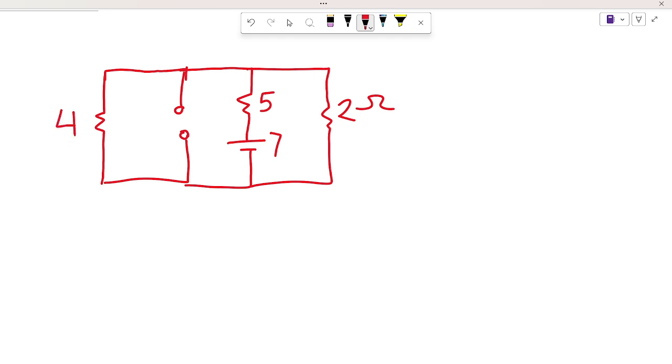So you realize in this case there's a break within our circuit. At this point there's a discontinuity in the circuit, and that's what we call an open circuit. The characteristic of an open circuit is that it has very high resistance. So the current wouldn't even want to pass through that part. It will go through the path of least resistance, as I said earlier. And since the open circuit has a very high resistance, it wouldn't want to pass in that direction.